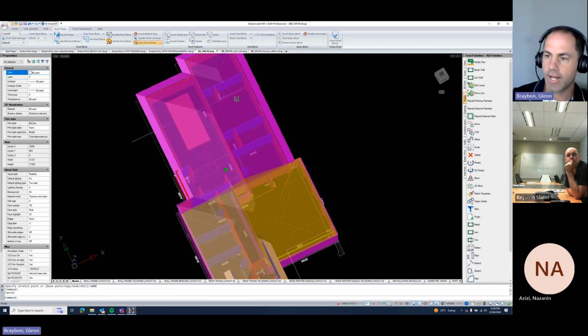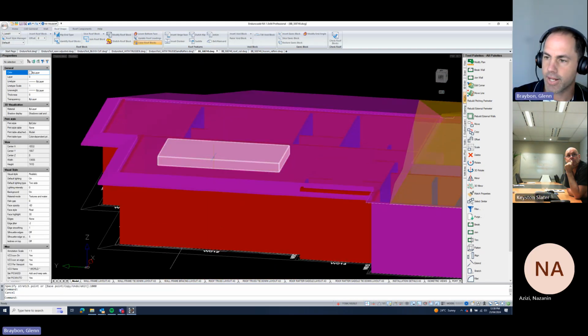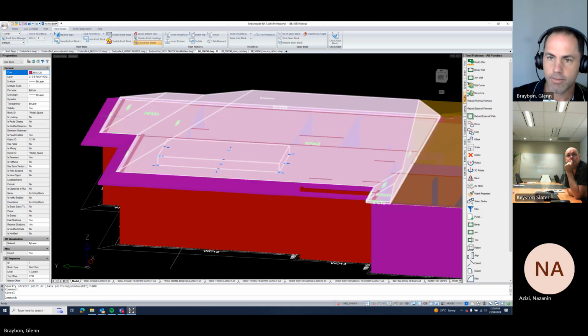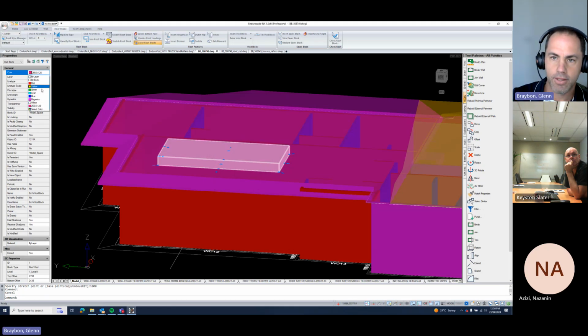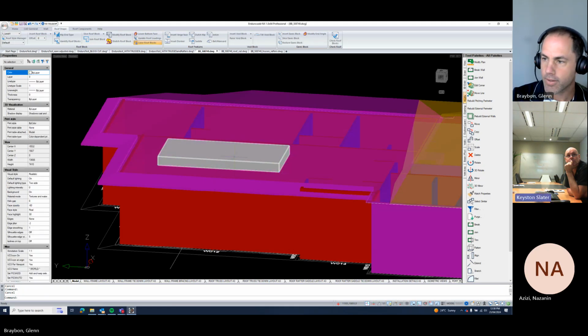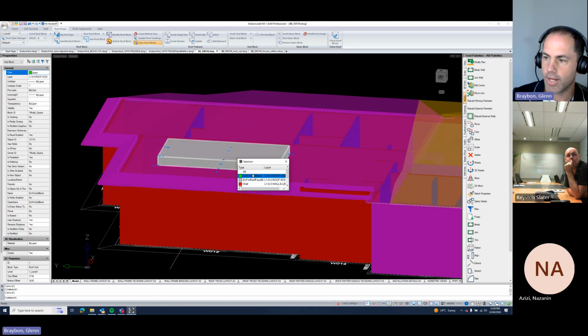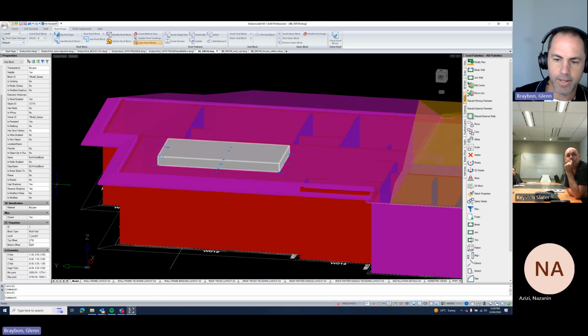Probably another good one to look at is, apologize for that color. Maybe I can change that here, Naz? Maybe here, make it green. So we've got a void block here. We're going to adjust the height in the properties menu. We can see here in the EC properties, we've got 2438. So we want to maybe increase that 200 mil higher. That's cool. Adjust it in that sense.